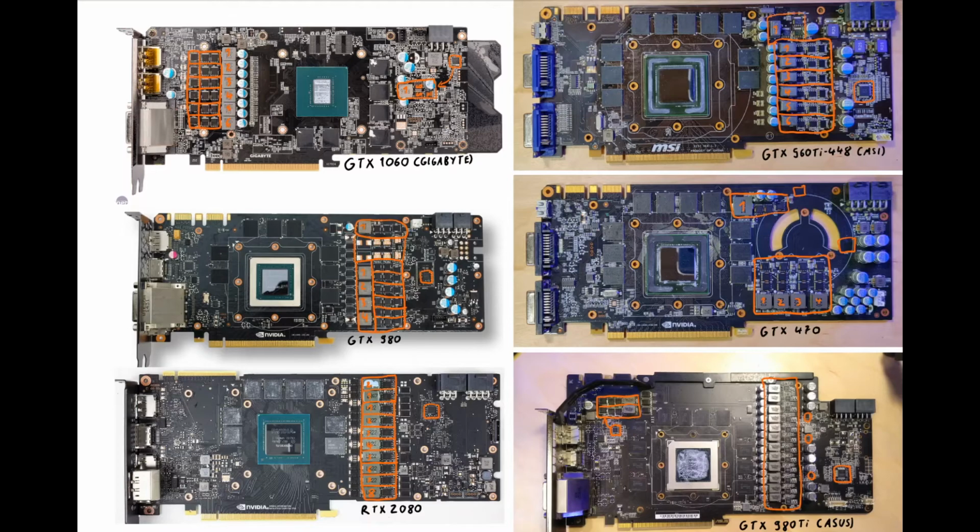So for example, the UP9512 of our 2080 down here, it can go from, I think, 1 megahertz, or is it 0.5 megahertz? I don't know, but it can go up all the way to 2 megahertz, which is very, very high. And I don't think any card will use this. Most cards will probably be somewhere between 500 to 700 kilohertz. And then Vmem VRMs will be somewhere around 300 kilohertz.